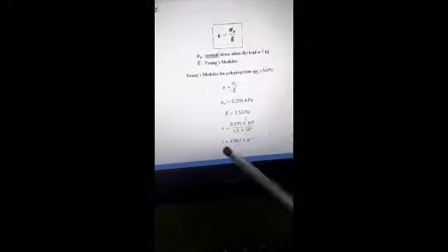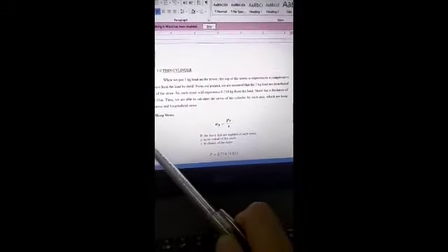So then for the third, the thin cylinder. When we put 5 kg load on the tower, the top of the tower is experienced as compressive force from the load itself. From our project, we assume that 5 kg are distributed to 7 of the straw. So each straw will experience 0.714 kg from the load.